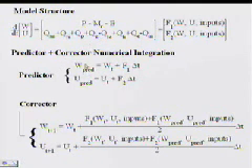So we take our first guess, if you will. The first prediction says the snow water equivalent at the end of the time step is the snow water equivalent at the beginning of the time step plus this rate of change from F1 times the length of the time step. And then we use a corrector approach.